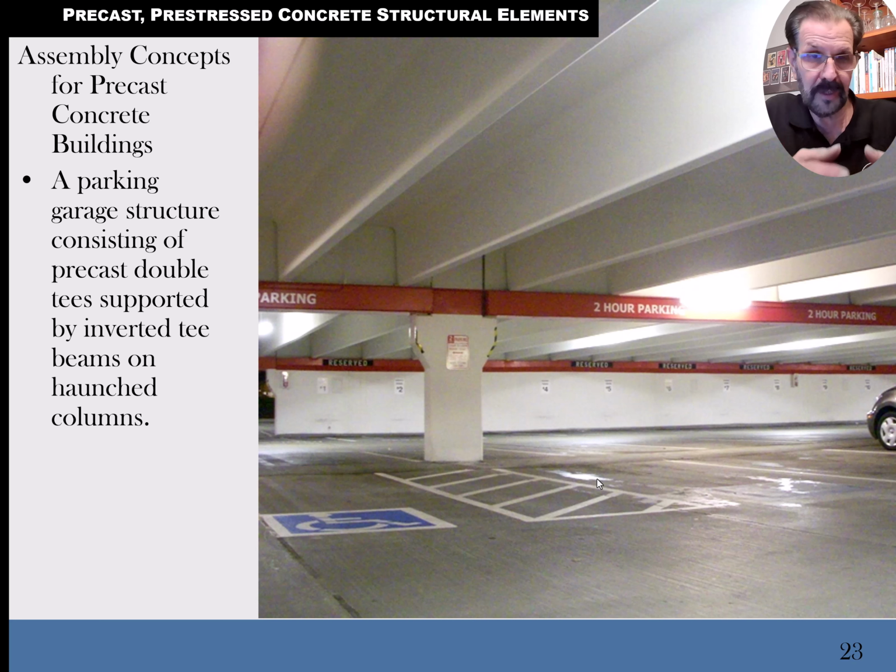It's just that we would mix in some aluminum powder to make it non-shrink, but we would also want it to be a zero slump mix for something like that, because we call it dry pack because we're literally packing it, oftentimes with pieces of 2x4 and beating it with a rubber hammer into the pocket where the grout is going to fit, and then it's smoothed out with rubber gloves on and stuff.